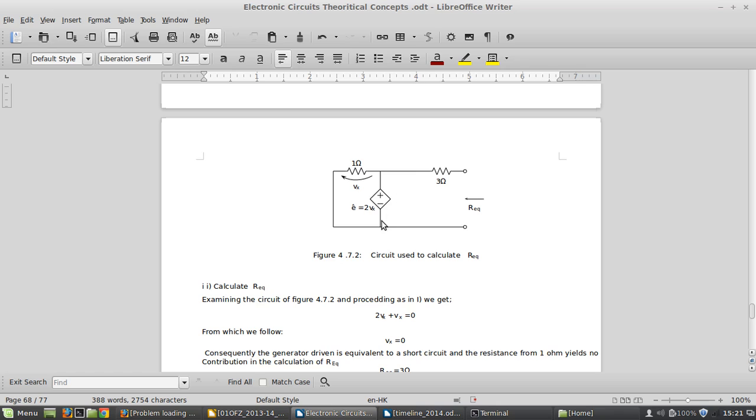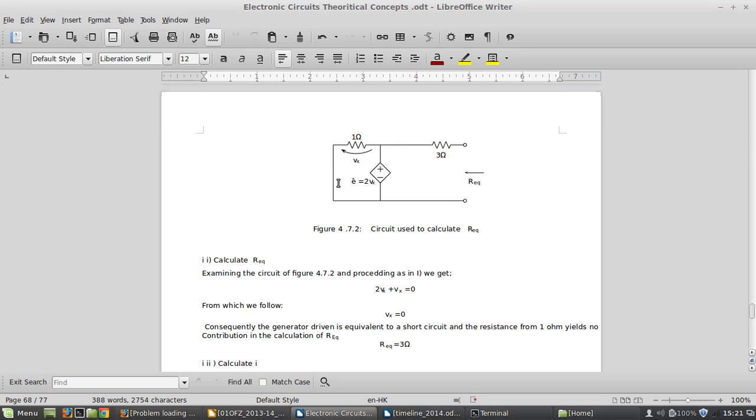If you check the voltage using Millman, the voltage flowing through here will be equal to the voltage flowing from here and the voltage flowing from here, because this branch has no effect, since it is floating. No current flows through here, and there is no voltage source here. No voltage also flows through here, so it is nullified.